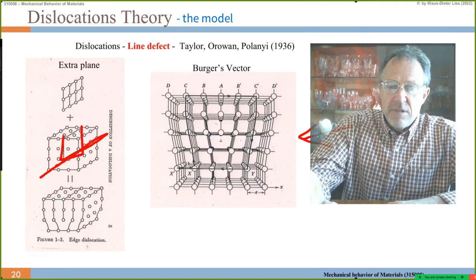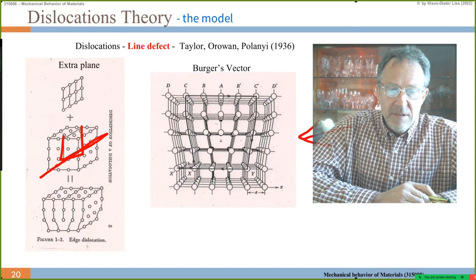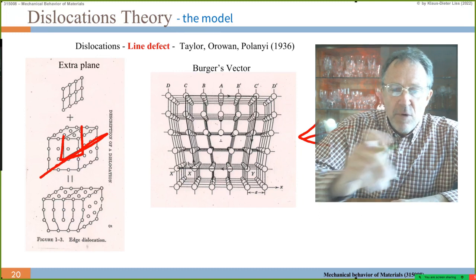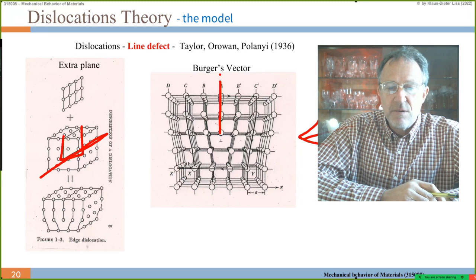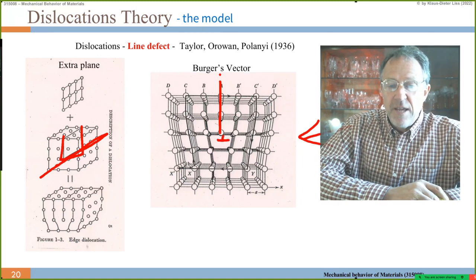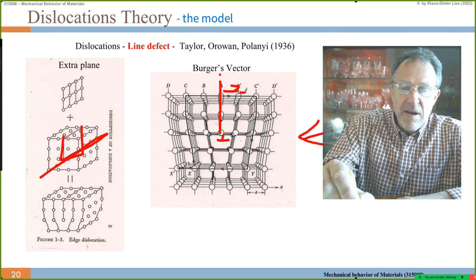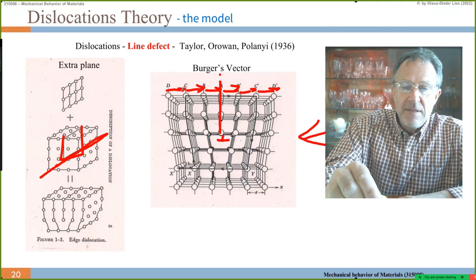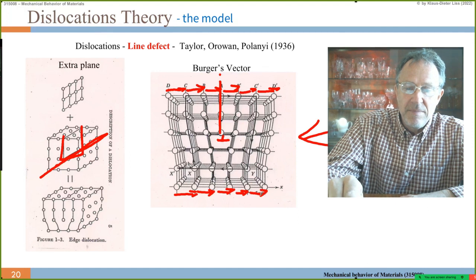I talked about the Burgers vector. We will talk more about the Burgers vector. Here, just shown in the 3D rendering, is the dislocation. So we have the one extra plane which is inserted half into the crystal until this line, the dislocation line, which is shown here. We look along the dislocation line in this case and see the upper atoms. Of course, here far away we have the lattice parameter, the translation invariant vector between the lattice atoms and lattice planes, and the same here at the bottom.